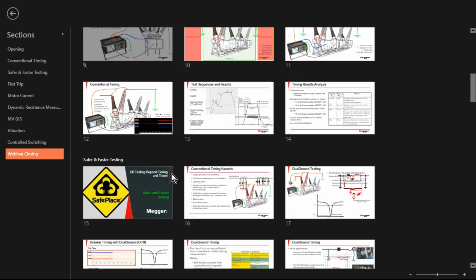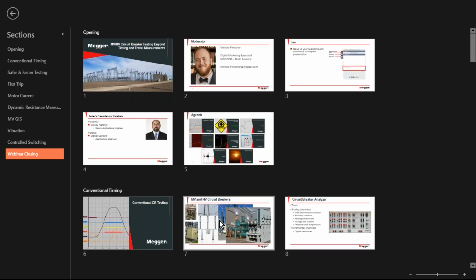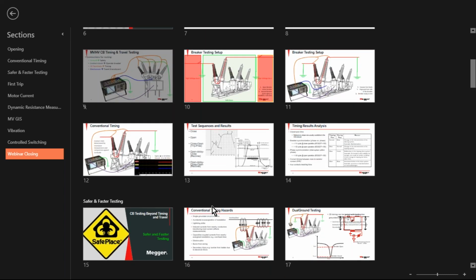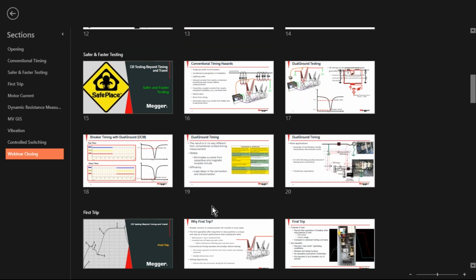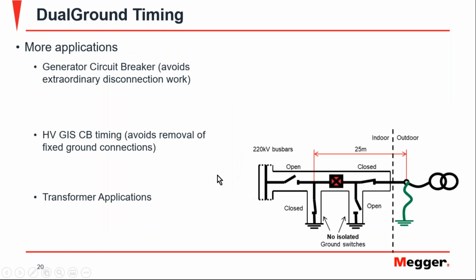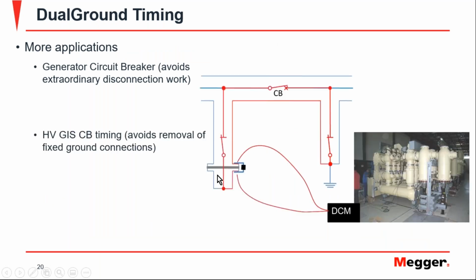It depends on the application, and basically boils down to that circuit to ground. How is that resistance compared to the resistance of the breaker under test? In this specific situation, for example, the one in the slide, sometimes that resistance is even lower than the actual circuit breaker.